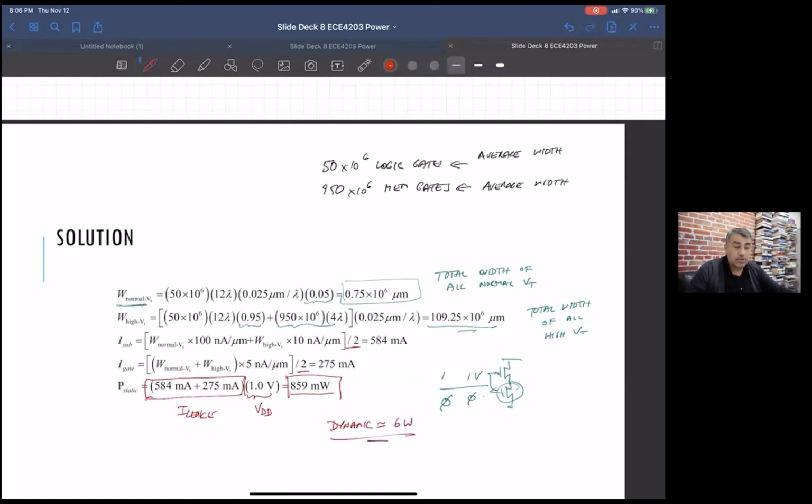Still pretty high. When I started doing CMOS design, unless you were doing analog design, you wouldn't even think about static power consumption. You basically just assumed it was 0 because you had these older processes, 0.18, whatever, where the leakage was really, really low. And even now, those older processes are still being used for a lot of biomedical circuits because people still have 0.35 micron and 0.5 micron processes.